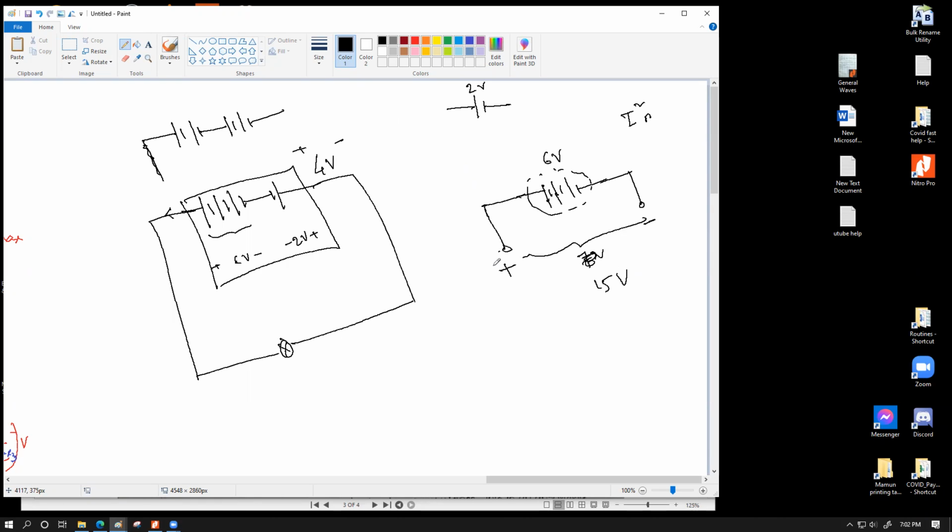That should be 9 volts, because now 6 will be cancelled out from the 15 volt. So you're now going to have a pretty large amount of current and you're going to charge up your battery really fast. But once again, because current is getting increased, the I square R loss is also increasing, which means your battery is going to heat up. And the moment your battery starts heating up, you start losing the quality or the life of the battery. Your battery is going to slowly start to perform less.